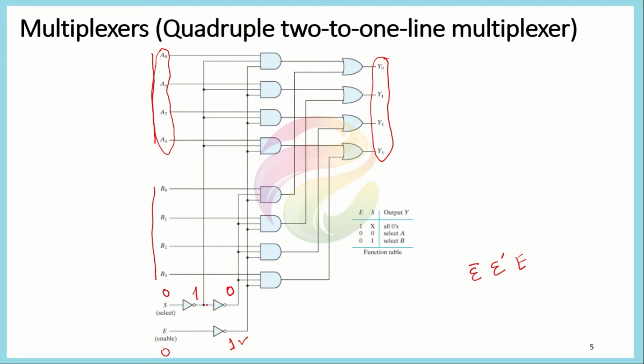So when we have this input here, the 1 will go to here, here, here, here, while 0 will be connecting to here, here, here. Because all these have zeros in the input, these AND gates will produce 0 at the output.